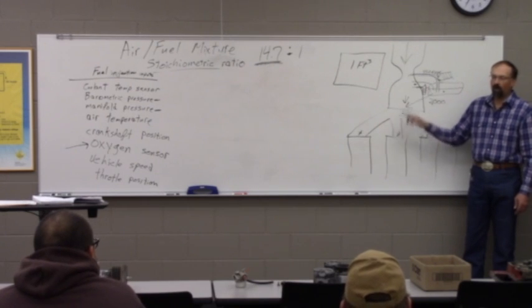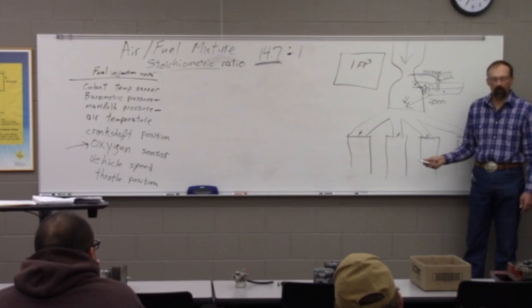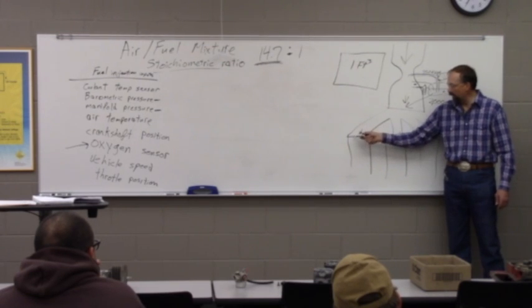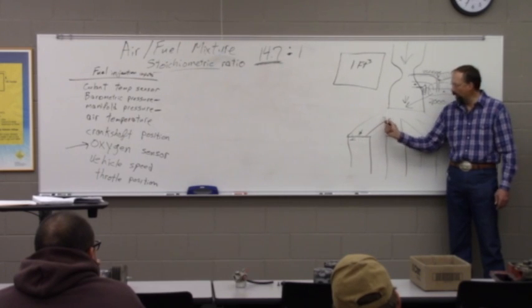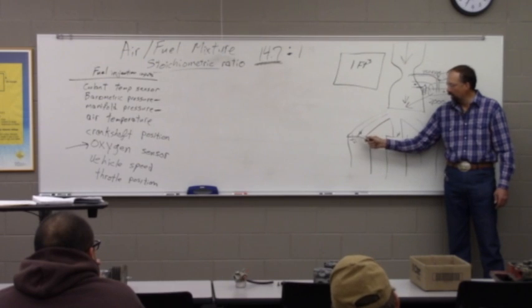So what's commonly done now is known as sequential multi-port fuel injection, where the computer's only firing this injector when this intake valve is open. So when there's actually airflow coming down this runner into the cylinder, we're going to squirt fuel at that point.